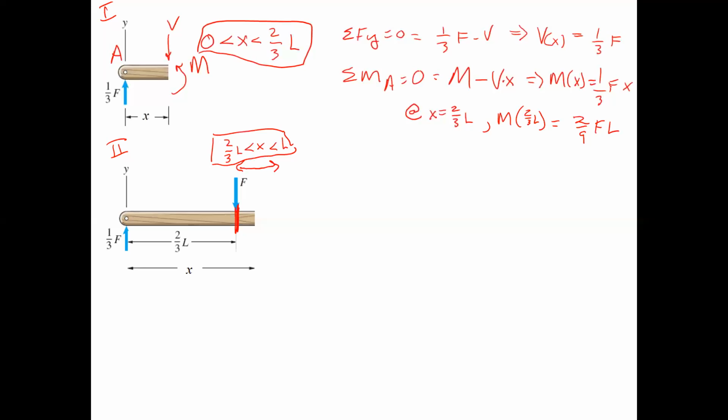In the bridge design, if you're going to do that extra credit, there are tables of the maximum tension and compressive loads for the balsa wood that you can use. Because it's a truss, the forces are very simple. They're either tension or compression. You don't have to worry about bending moments or shear forces. Because there are only two-force members, the forces are all going to be normal forces only. But with other structures like frames, you have these various forces going on.